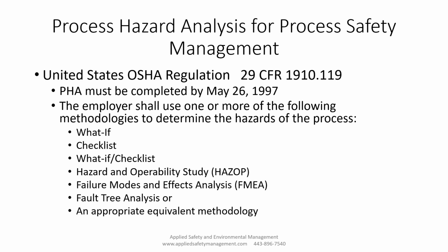So the different methodologies out there, you can use the what if, you can use a checklist, a combination of what if and checklist. There's also the hazard and operability study, also known as a HAZOP, failure modes and effect analysis, the FMEA, fault tree analysis, or an appropriate equivalent methodology, which is just a really fancy way of saying with all these different ways and checklists and things, you have to have a way that you're analyzing your entire process.